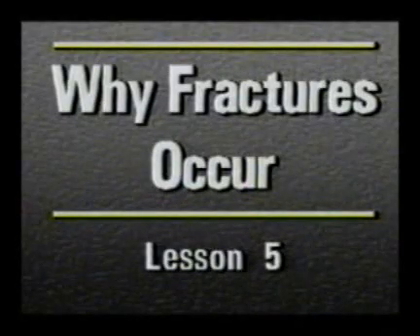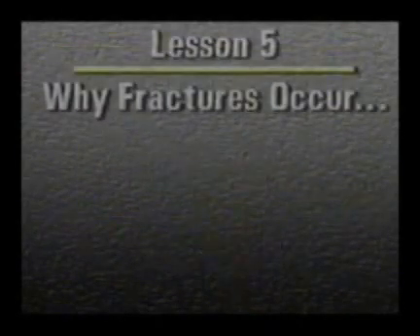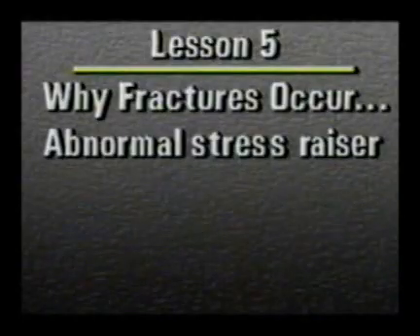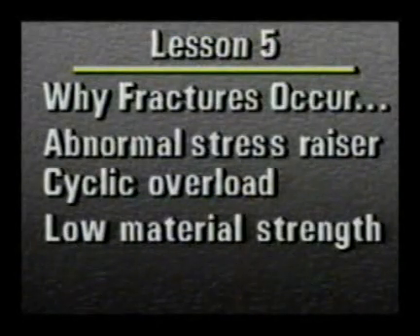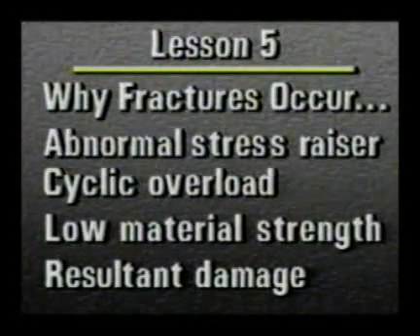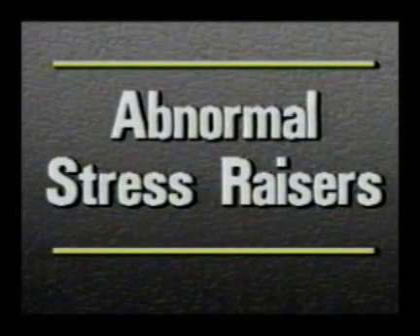Once we locate the fracture initiation site, we are nearing our objective to determine why the fracture occurred. In this lesson, you'll learn to recognize whether a fracture occurred due to an abnormal stress raiser, cyclic overload, low material strength, or damage resulting from abusing the equipment or from another part that has already failed. Let's look first at abnormal stress raisers.